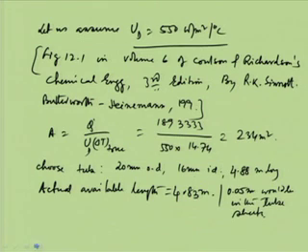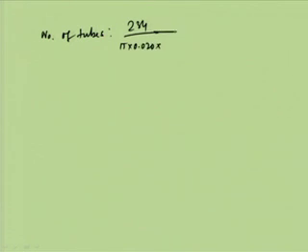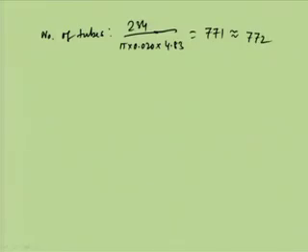The standard tube size is being taken, and then once we have identified the tube, we know the area. So, the number of tubes is equal to 234, the total area, divided by pi into d into L, that is pi into 0.020 into 4.83 meter, the available length. This way it becomes 771. I am approximating it to an even number, because we know that there will be 2 tube passes. So, I am putting it to be 772.